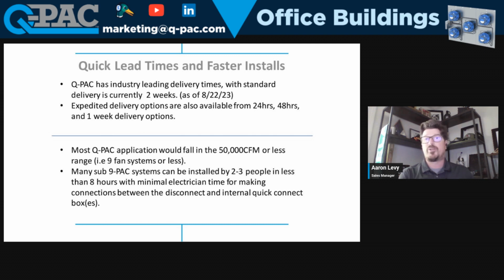Very minimal work from the electrician side. They normally come in and make their landing points. In most cases, they're doing it over a weekend, so BMS may not be available to come in and land their stuff until an actual business day. But the electrician can come in and make his line voltage connections to everything. And once the fans have line voltage, you should be able to run the system in hand mode to at least get air going until BMS comes and lands their points.